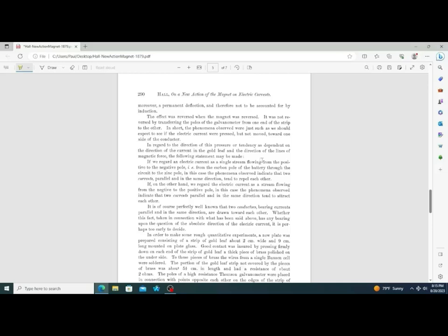Now, the way it's visualized now, and I don't know if I get a chance, maybe I can try and find some images for it, but the way it's visualized now is that the magnetic field will either pull or push some of the electrons to one side of the wire. So if you figure you have some of the electrons going to one side of the wire, that'll develop a negative, and in sympathy the other side will develop a positive pole. And so you have this positive and negative that develop orthogonal, 90 degrees apart from the direction of the current flow, and that's the Hall effect.